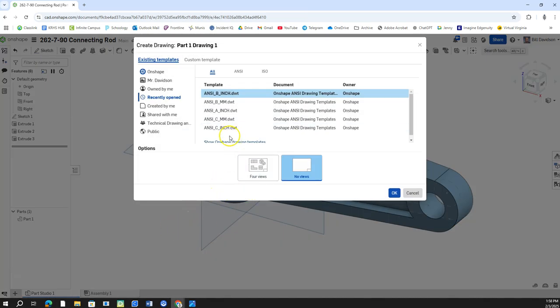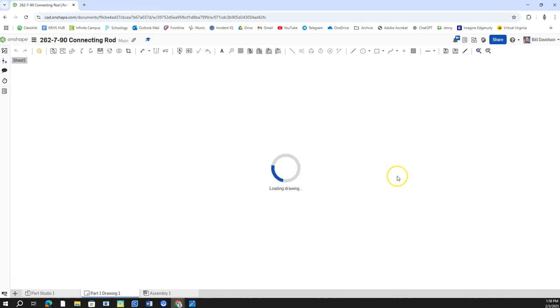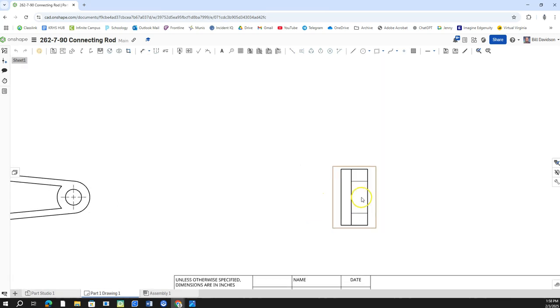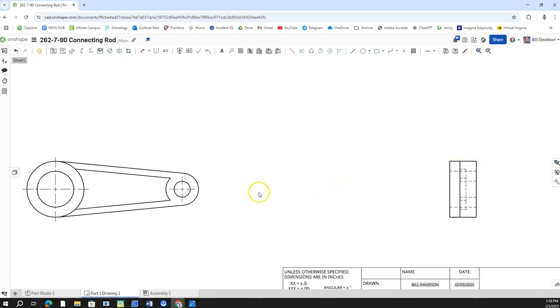And when we create the drawing, I'm going to start with inches and do 4 standard views, and this should become evident at this point what we're doing, because our right side view should be our smallest view, and this one gives us the lowest number of hidden lines if we do it this way. So I'm going to hide all my tangent edges, and I'm going to show my hidden lines going through, and that gets a little complex.